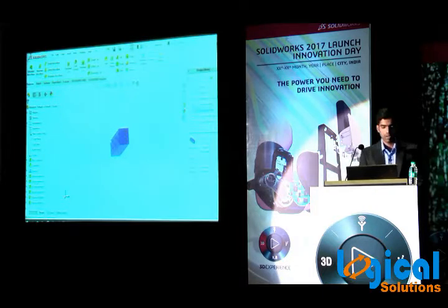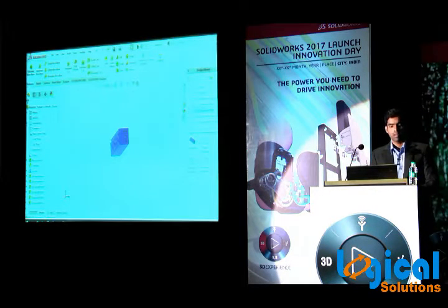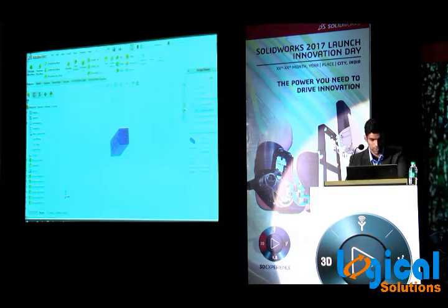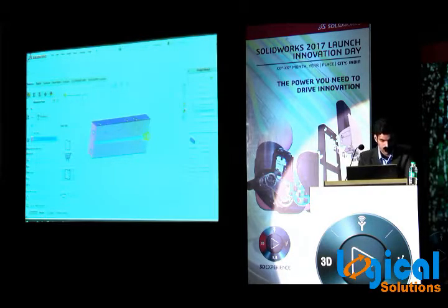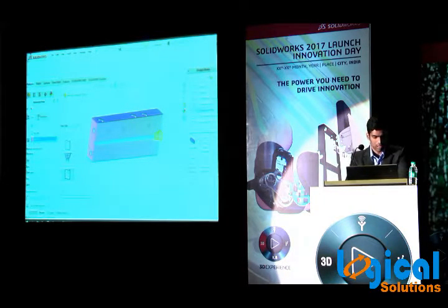In advanced holes you can add different sizes at a time, like taking a section view here. If you want to change the size, like near side counterbore or near side countersink, you can select it and give the end conditions. Like type, I am going to select drill size and give the size. I am going to give 9, and if you want to add one more to this, you can just click insert elements below active element. If you click this, one more will be added and you can control this again.